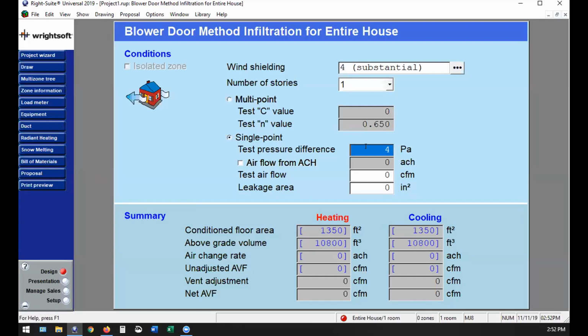And we did blower door testing at every step of the way. And the first blower door test we did, we almost didn't get it down to 50 pascals. We actually had to put some weather stripping on the back doors just to get it down. It was having trouble on this little tiny house. Wow. Having trouble getting it. Yeah. So good luck even imagining how leaky the place was at that point. Right. But there are homes where you can't get it down to 50. So you could change it to a different test pressure difference. You could do this at 25, which is something that has been done before.